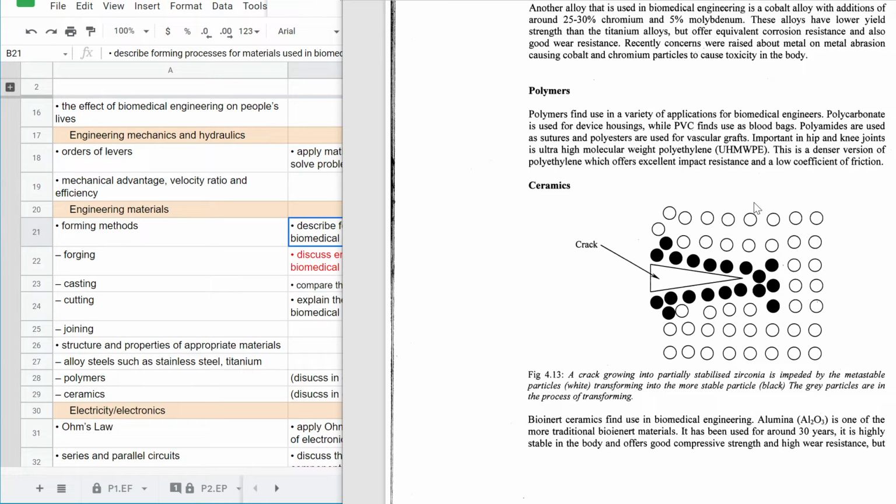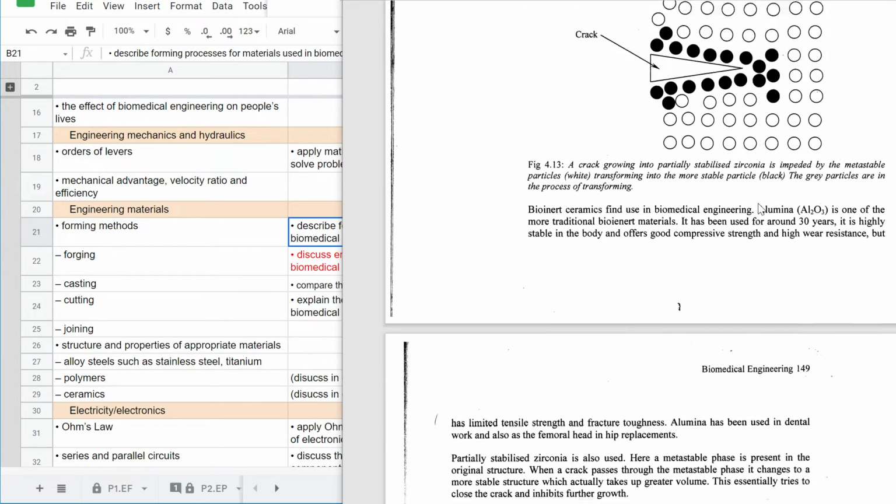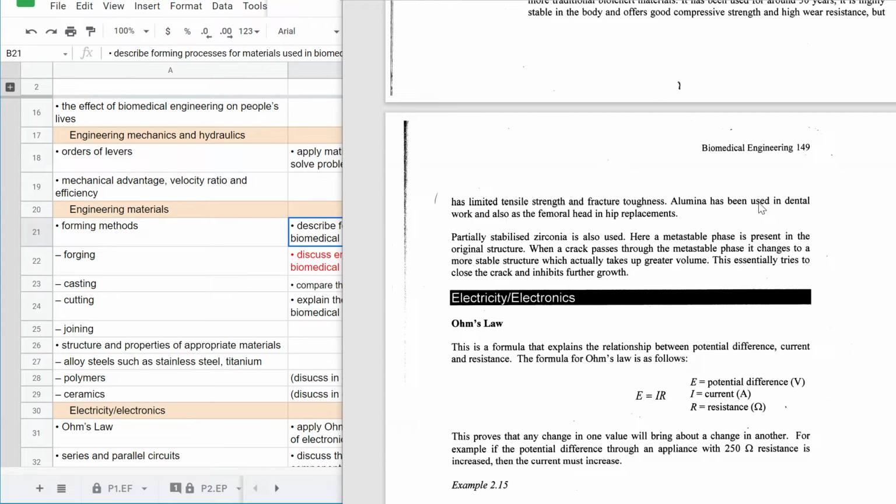And so by filling up the crack, it reduces the voids and it stops crack propagation. Now, generally, when we talk about preventing crack propagation, and we'll talk about this next year, when you start to see cracks, what you do to stop cracks spreading in an engineering context is you drill a hole at the start of the crack, and that makes it harder for the crack to spread. But that's the advantage of using zirconia in alumina. So alumina has good properties, and zirconia can help us to improve the properties of alumina.